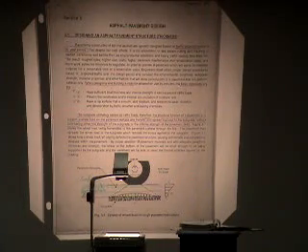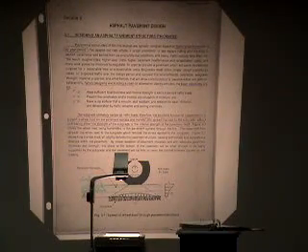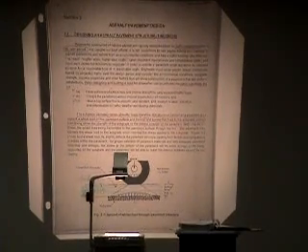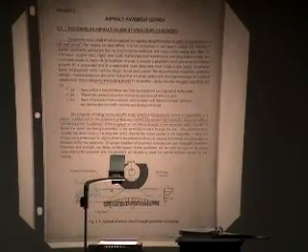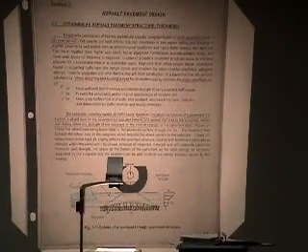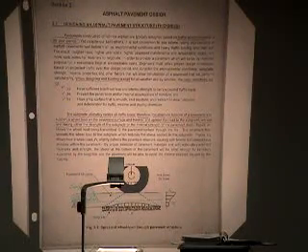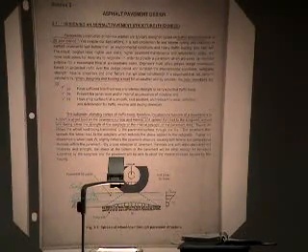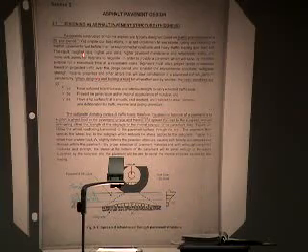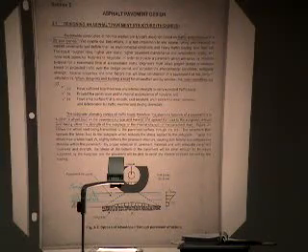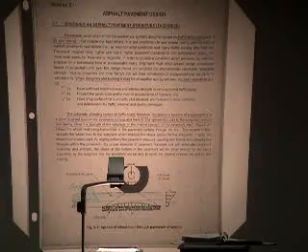Hopefully with adequate maintenance as you went along, proper resurfacing, at the end of 20 years, you could do some major rehab work and establish that pavement such that it would last for another 20 years. But generally, you base it on a 20-year design period, and you want to come up with a pavement thickness that's thick enough to carry that projected traffic.